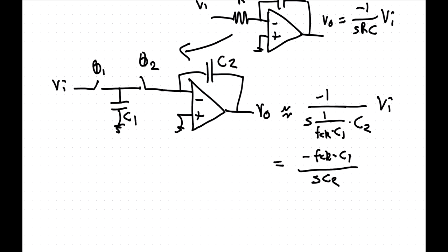Isn't this just like an origin pole? Like output zero frequency, like DC? Yeah, it's an integrator. So then probably wouldn't go around much, right? You probably have some feedback around that, otherwise it'll saturate.